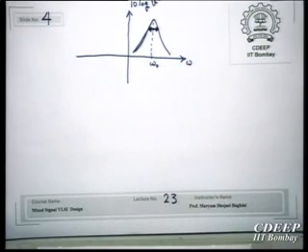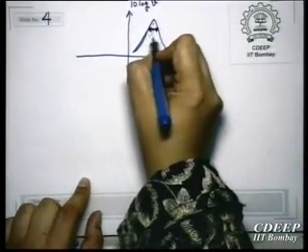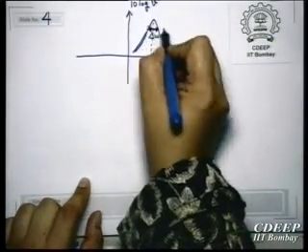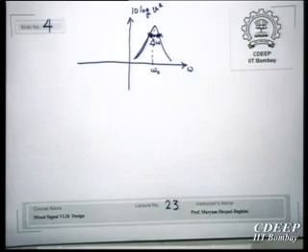Now, what is jitter? Jitter actually is the same thing. If the frequency of a signal changes by a small amount, that is called an offset, so this is delta omega. For example, usually phase noise is mentioned as per the offset from a carrier. So now in the clock, in digital systems, if you have a clock generator, say a 500 megahertz clock generator, there are different